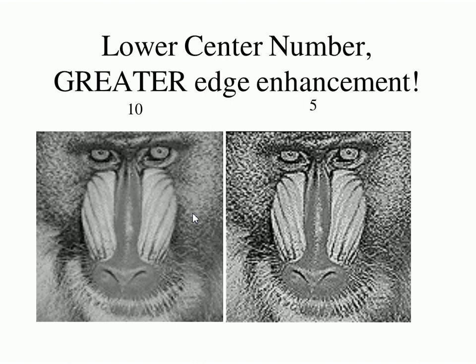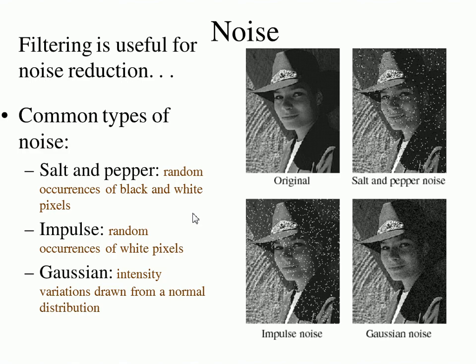So in general, before you apply such a filter, if you want to be reasonable about the kinds of edges that will be detected after you apply the filter, you first do a low-pass filter, then you look for the sudden changes of noise, and then you do a threshold detection. And that's how you normally do edge detection. So why is that true? Well, the reason why is because when you take a derivative, if there's a sudden change in a function, the derivative is not well defined, right?